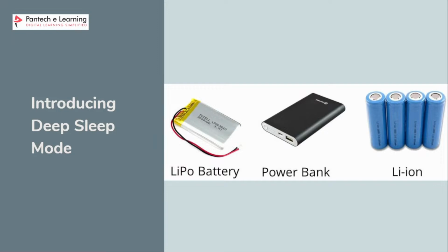If you put your ESP8266 in deep sleep mode, it reduces power consumption and your batteries will last longer, right? Having the ESP8266 in deep sleep mode means cutting the activities that consume more power while operating, like Wi-Fi, but leaving just enough activity to wake up the processor when something interesting happens.